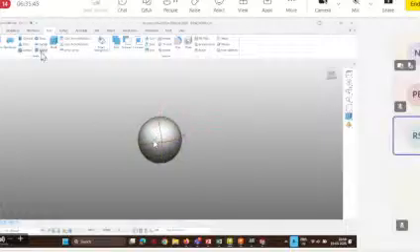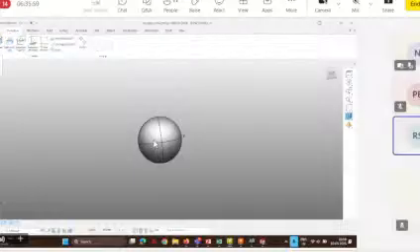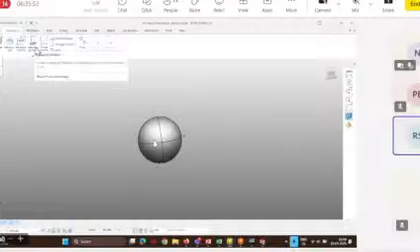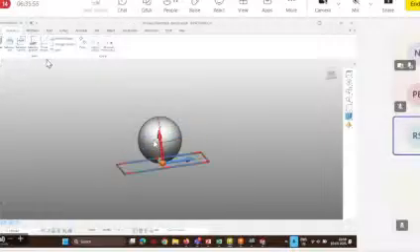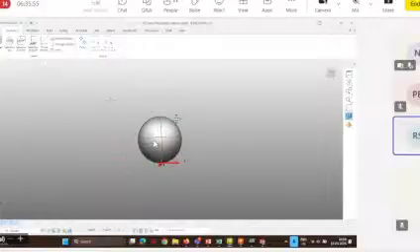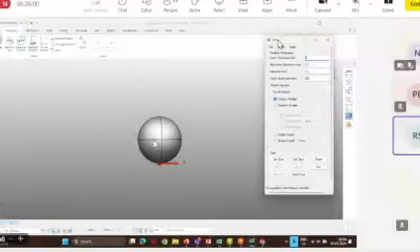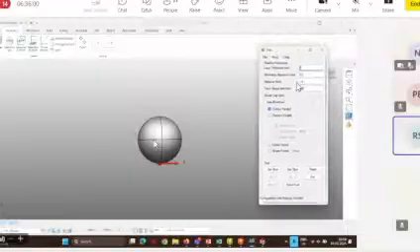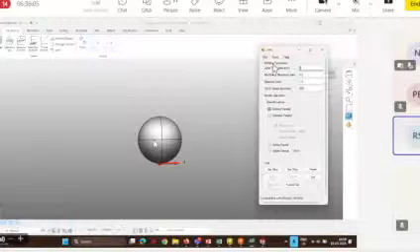Now I can create another workflow at the bottom of it, which will help us in generating the slicing plane. So select it and create a workflow at the bottom. All right. So now we have developed this same software in IIT Guwahati using macro only. Here you can define the layer thickness, maybe 2. Then the machining allowance you can specify over here. And then this is the step over, you can mention maybe 3 mm. Then you can set the deposition speed, so maybe 1000.